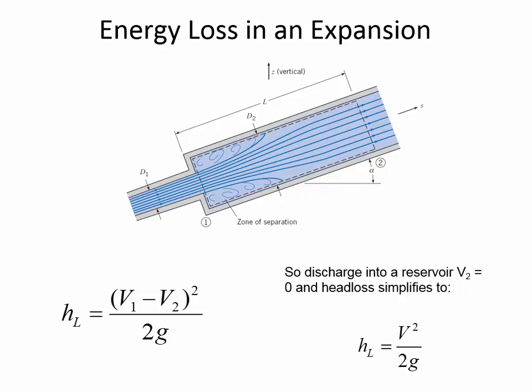So here, this is saying the head loss is equal to the velocity head. You're losing all of the velocity head when water enters a tank. That's something you need to make sure to show when we're doing these drawings of energy in systems.